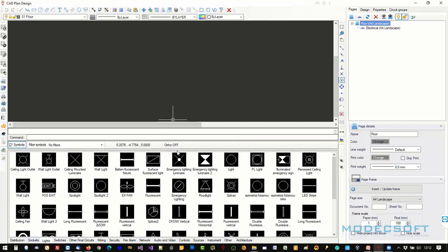Yes, Spencer? Just sort of paraphrase that a little. So various elements here, certain things that will be put on there will not count as adding to the number of points. So where we're doing a design and you have a circuit, say like a socket circuit, if you were to put something like an instrument, such as a meter in there, it wouldn't count it as an additional socket out there. So during the design, it won't add on an additional load because it understands that that element from that item doesn't need to be counted in that way. So various elements have little properties like that to help along with the design and avoid additional loads being added where they're not necessary. Yeah, thank you for that.